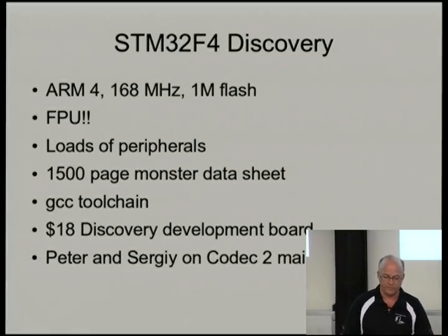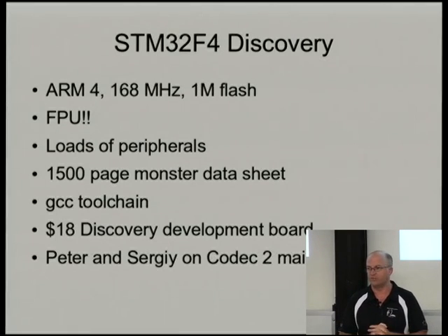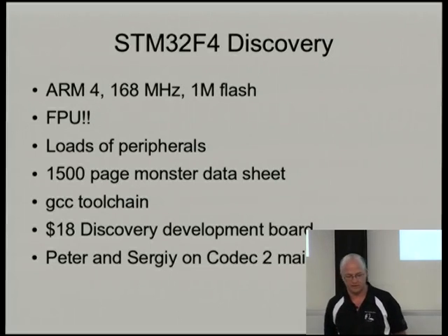It's got loads of peripherals, this chip. A monster data sheet. Just to make GPIOs flash, you need 8 or 9 register programs and things like that, because it's so flexible and so many things you can do. So a bit of a steep learning curve. It's not like using a PIC or something like that, or a simple AVR. There's a fair bit more to it. But fortunately, there's plenty of examples around, and eventually we can get going on it.